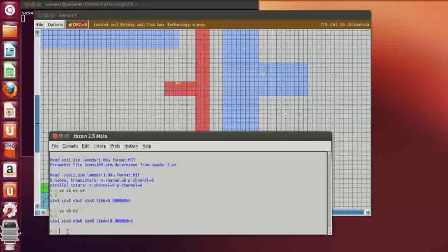Let me give high value to VC. So certainly we'll get the output as 0. Why? This is 0 0 and the AND output will be 0. This is 1, so OR output will be 1 and the invert will be 0 again. So if I give high for VA, again that will be 0 because VB is 0.